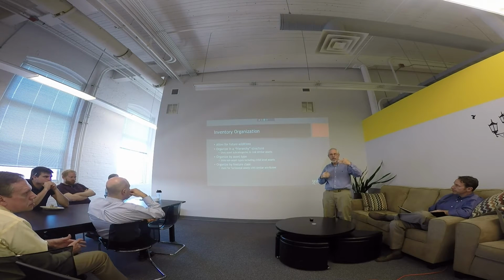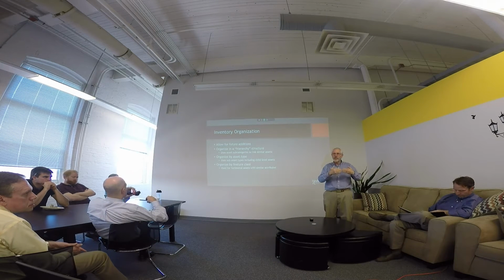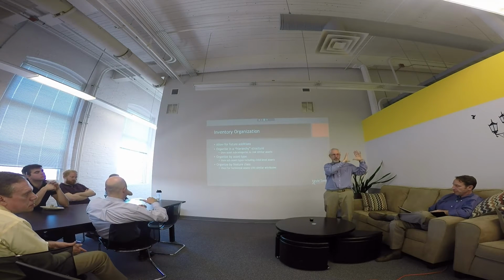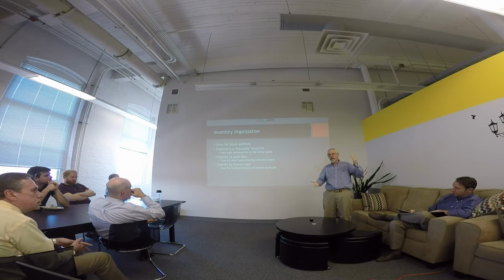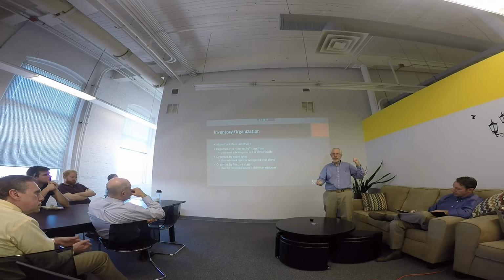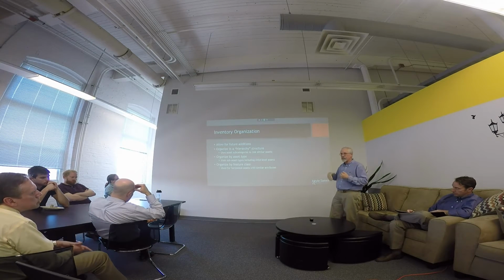Because you may have a generator, and attached to the generator is the fuel system that feeds it. And then if you want to break it down, you can break it down to the starter motor, the radiator. So all of a sudden, it goes from the treatment plant to the generator room to all these other levels. Typically they recommend you go down 7 levels of hierarchy to really be able to manage your assets and understand what's failing and what's not failing. So it's important to go through that process with a client on what you need.